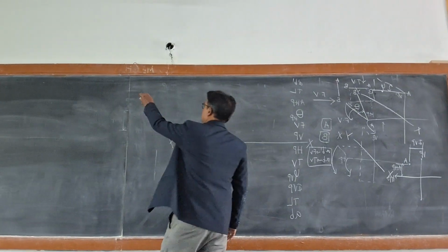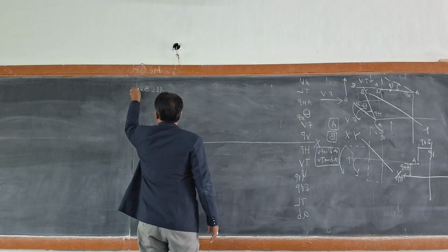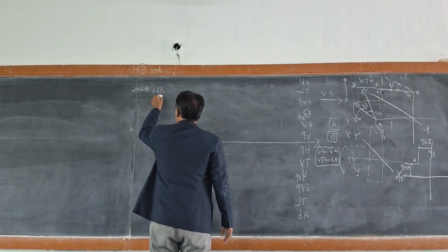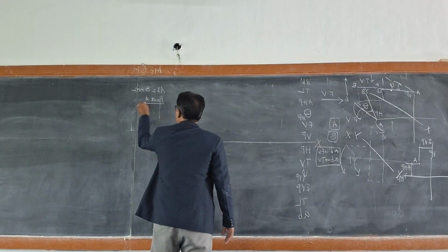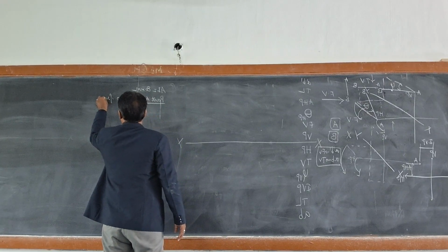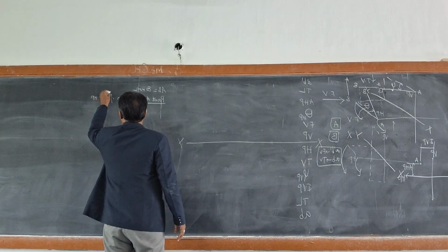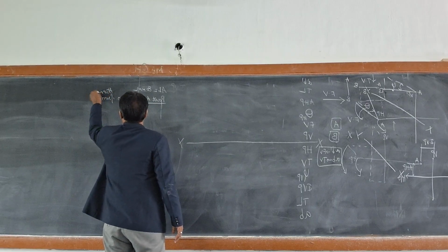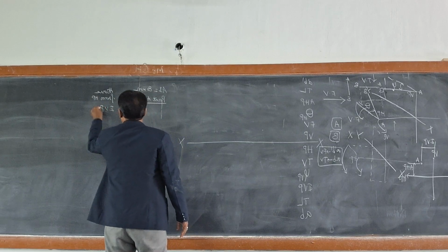Now let us assume there is a straight line AB which is 80 mm in length. Then this point A is fully defined, which is 10 mm from HP, that is what you call as above HP, and 20 mm in front of VP.